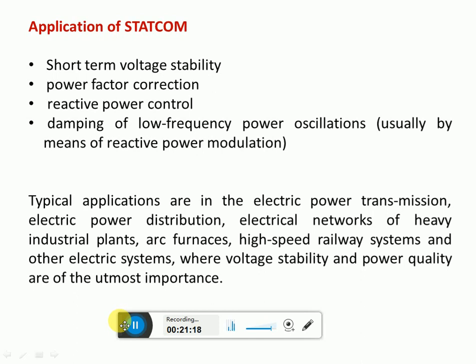Power factor correction is possible using the STATCOM, and as already seen, reactive power flow control is possible by controlling the output voltage at the terminals of the voltage source converter.